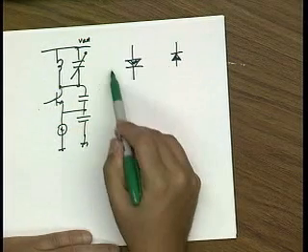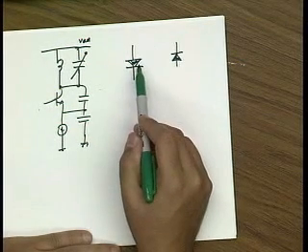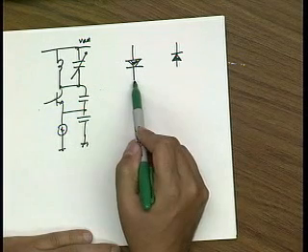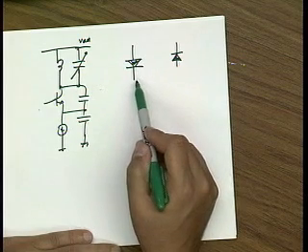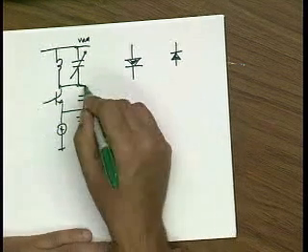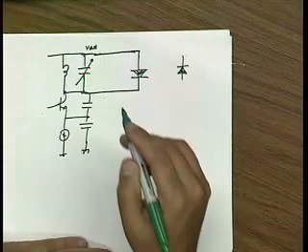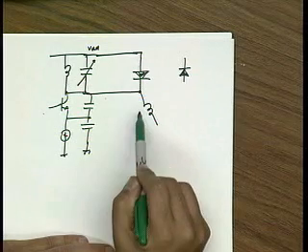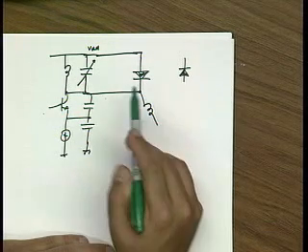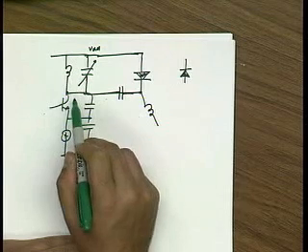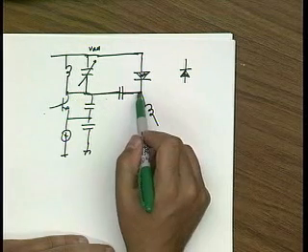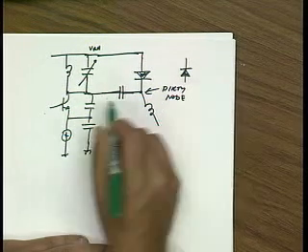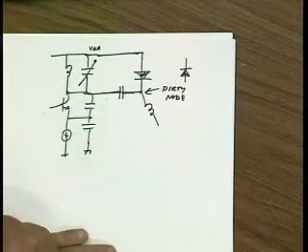And so if I use this configuration, first of all, it would put the dirty node onto my tank. And second of all, I would need a voltage larger than VDD to reverse bias it, right? So in order to reverse bias this, I'd have to use a voltage larger than VDD. That means I'd have to put a cap here to avoid connecting that here. And this dirty node is connected to my tank, right?